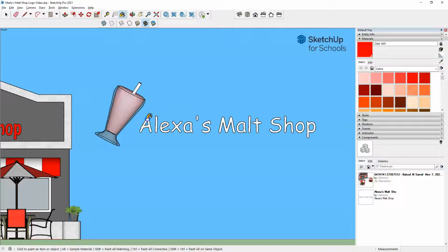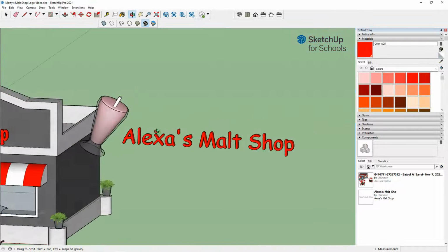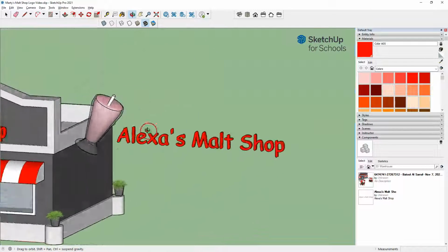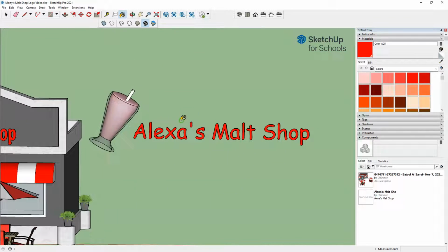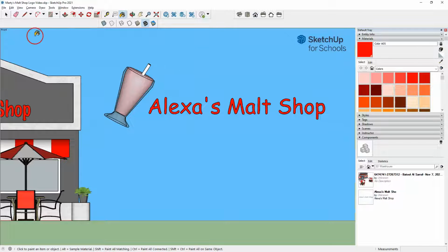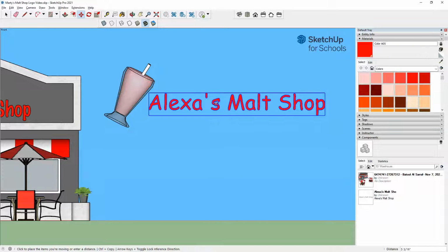I will select my font there, and if we look on an angle, we can see that it was extruded to the 5 inches deep. Looking at the front view again, I may choose to move that text over. That looks pretty good where it is. If I wanted to, I could just use the move command and place that accordingly.